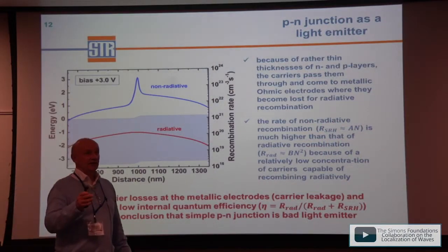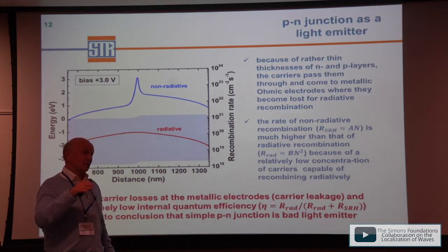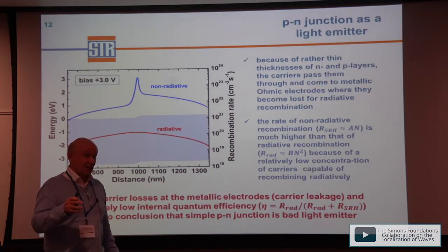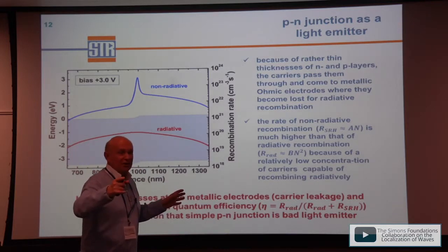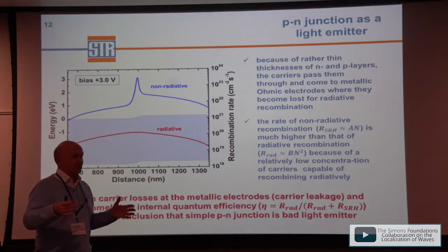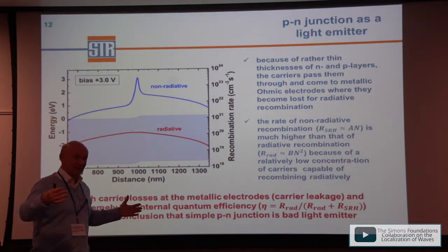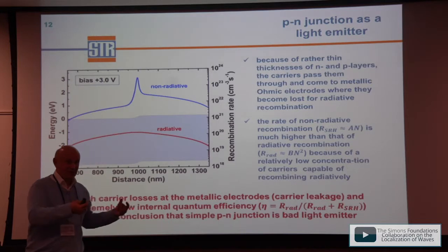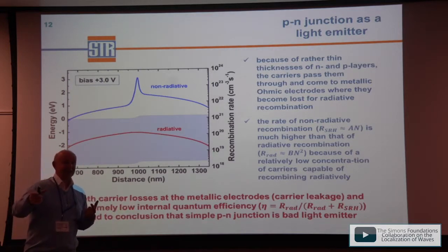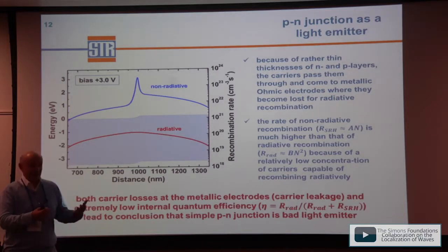The typical diffusion length of aluminum gallium arsenide lasers is from 2 to 5 micrometers. So if the thickness of the structure is less than the diffusion length, or maybe 2 diffusion lengths, leakage will be pronounced too. If the structure, for instance a pin junction, has a thickness of 100 micrometers, we don't see the leakage current because all the carriers have enough time to recombine on the path to the electrodes. So it depends on the competition of recombination.